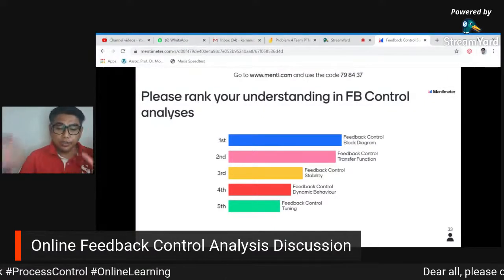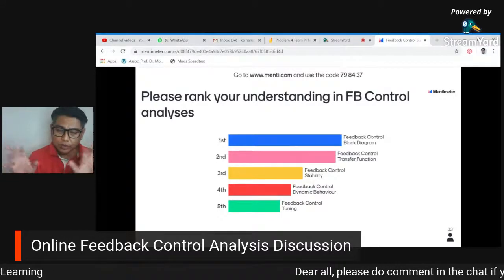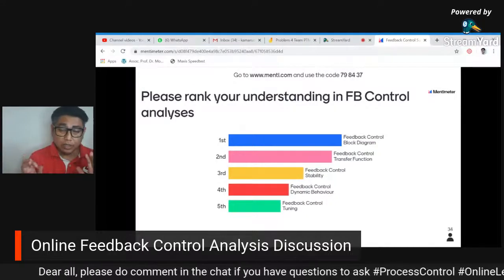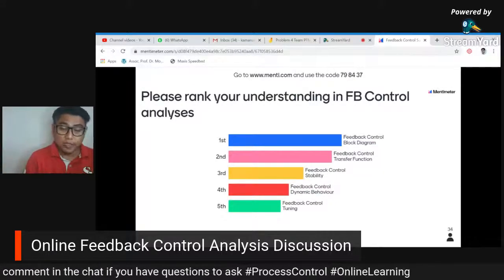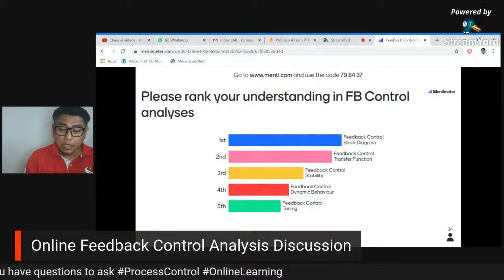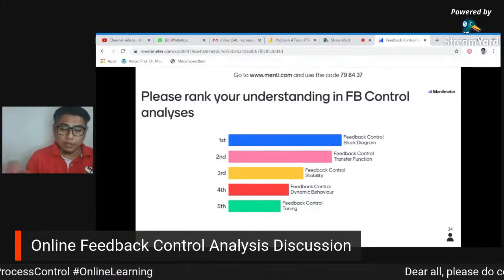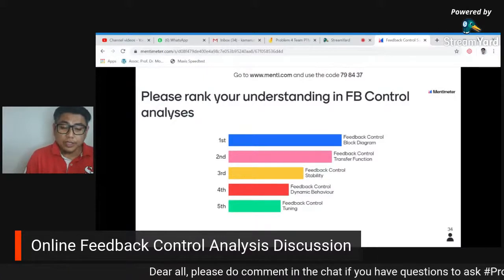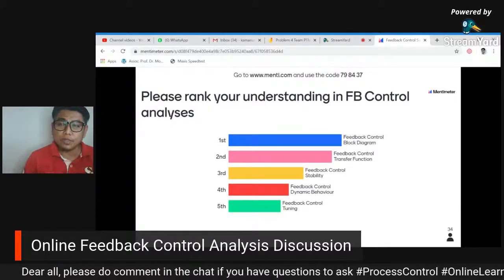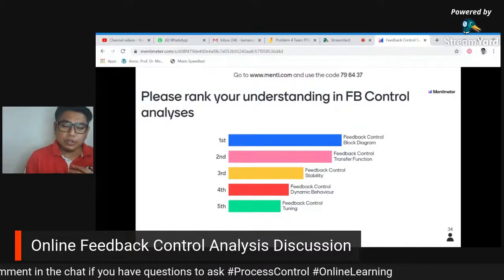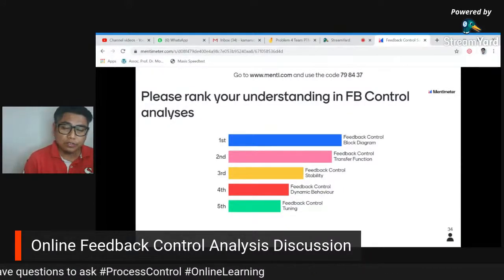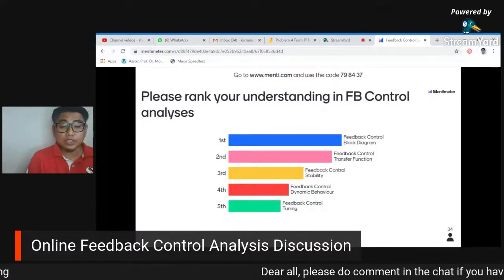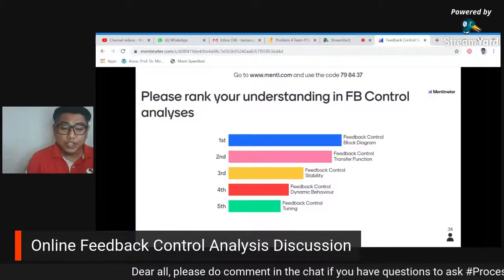You need to first draw the block diagram, put in all the values, label all the streams, and after that you develop a transfer function, or derive it if the question asks you to. Otherwise, you just pick either the servo or the regulator, depending on the question asked. Then you transfer all the values into this transfer function and simplify the equation.